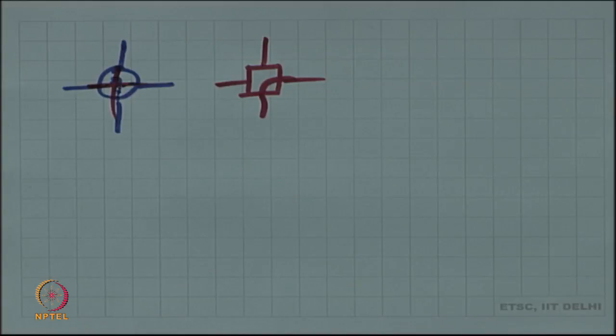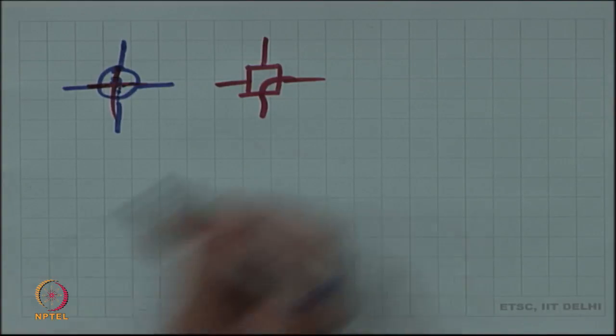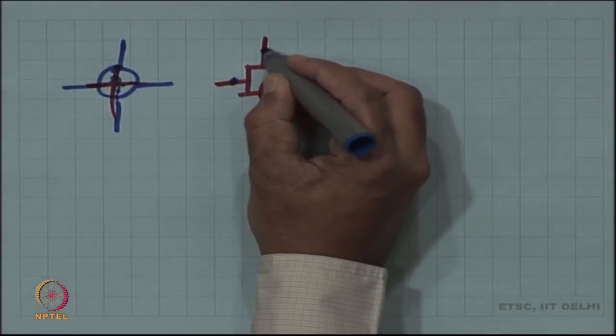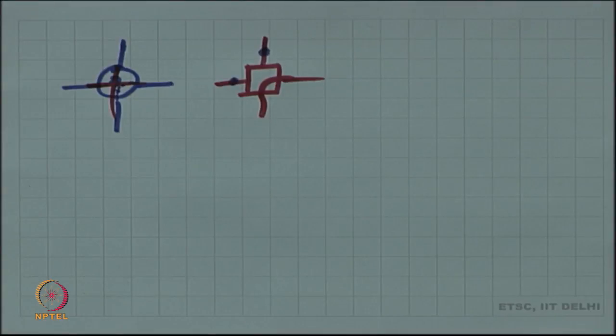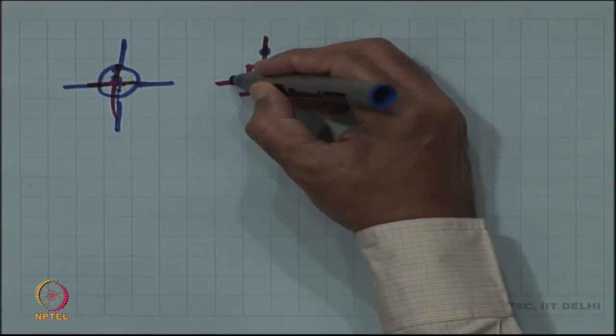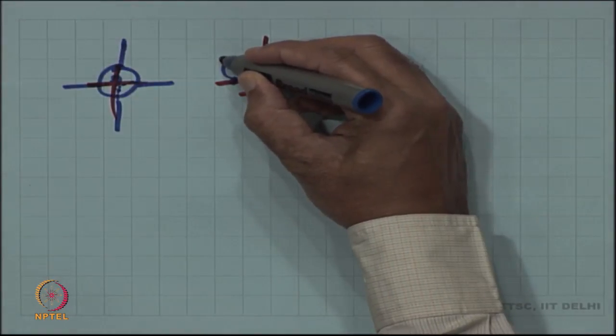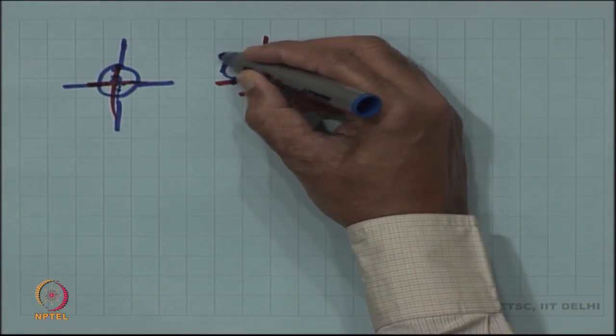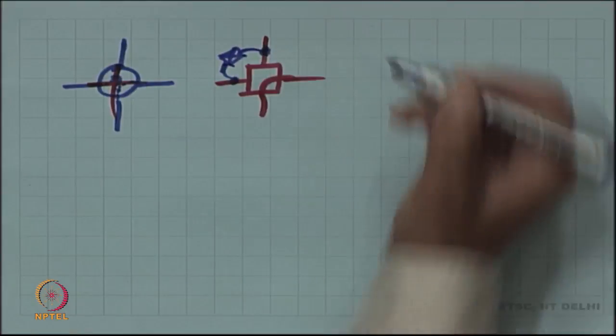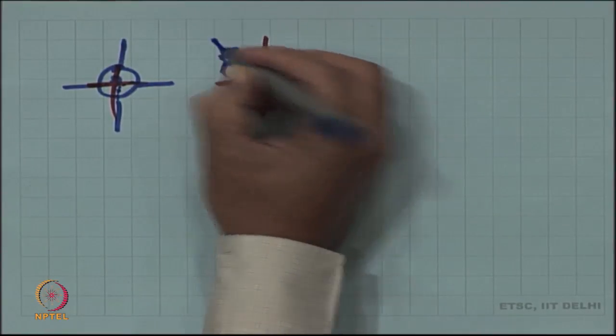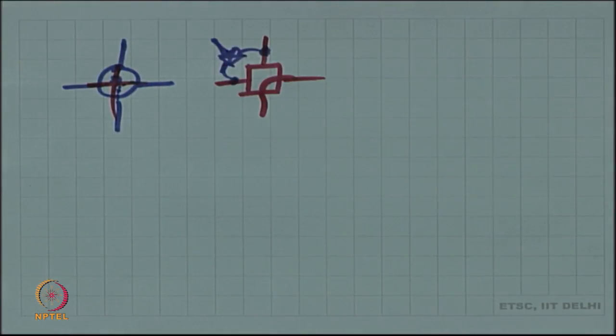Essentially, between every pair of terminals that you would like to offer the programmability feature, either they are connected or not connected, essentially you would have maybe a kind of a transmission gate in which the control is determined by our memory cell.